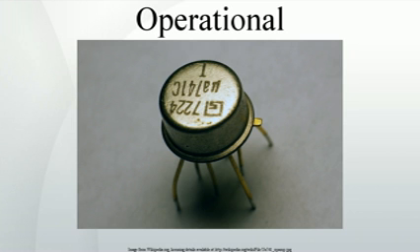Transistor Q7 drives Q5 and Q6 into conduction until their equal collector currents match that of Q1/Q3 and Q2/Q4. The quiescent current in Q7 is VBE/50K, about 35 μA, as is the quiescent current in Q15, with its matching operating point. Thus, the quiescent currents are pairwise matched in Q1/Q2, Q3/Q4, Q5/Q6, and Q7/Q15.